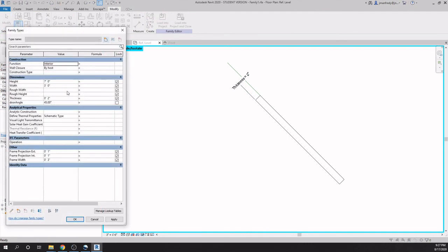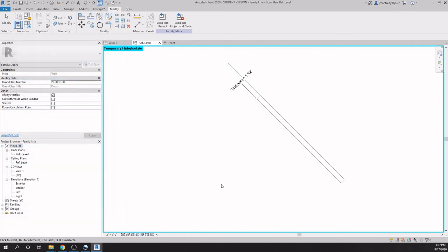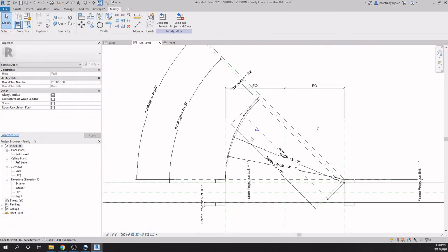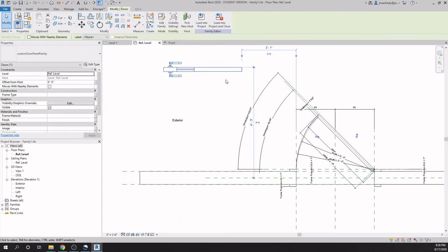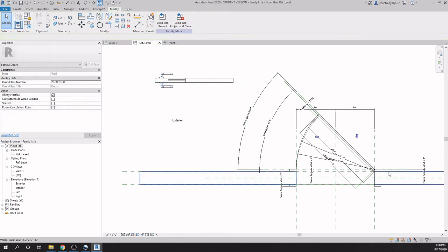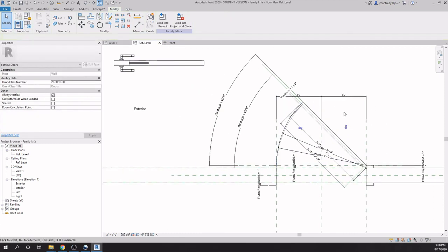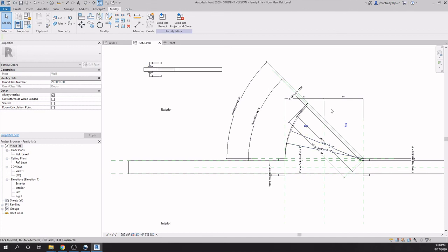And here we'll set the parameter to 1.5, and we'll see this door change thickness in a second. Hit apply, and you see the door just changed. So now it's controlled by the parameter. That's great. This is done. So, with that aside, here we want to do the same kind of controls to this door. This door has its own family, and this door is currently nested or copied into this door template. So this is nested into this.